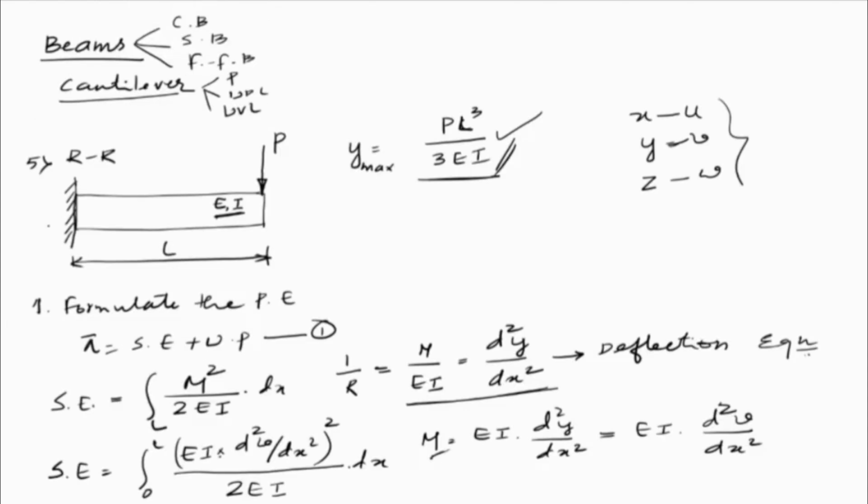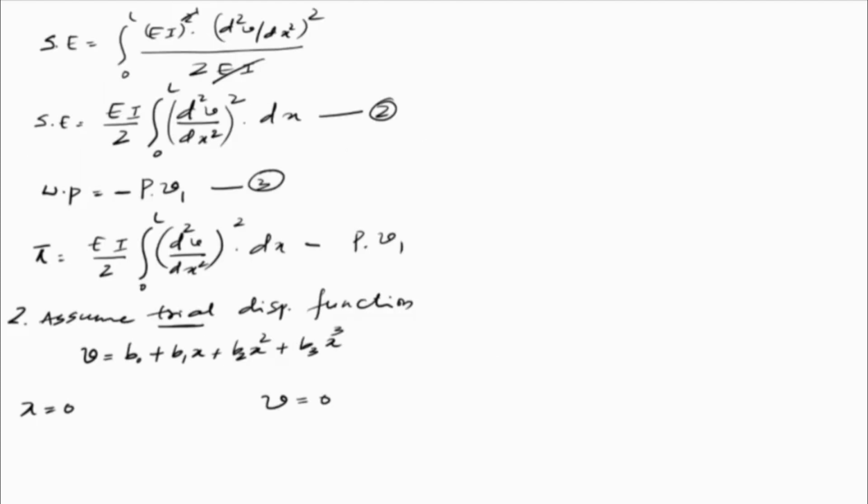So in this beam, here x is equal to 0, and here I have x is equal to L. So when x is equal to 0, my displacement is 0 because it is a fixed end. Therefore, substituting v is equal to 0 and wherever x has 0. So what am I going to get?